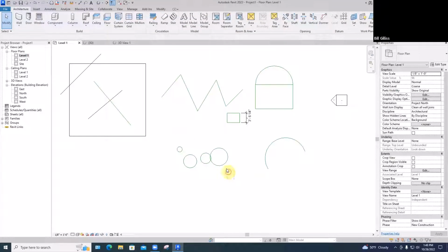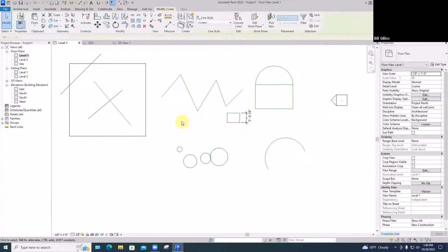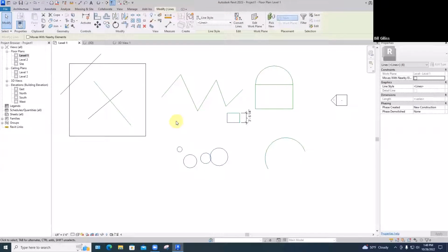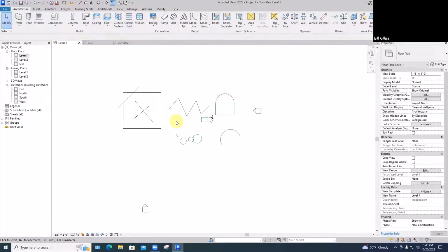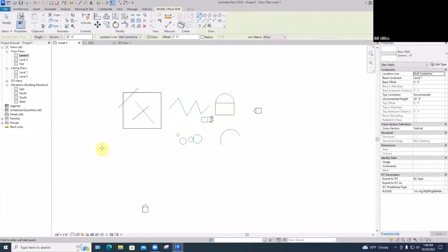Dragging from right to left, as in AutoCAD, puts up the rectangle with the dotted lines, which is a cue that as soon as anything is even touched by the rectangle, the whole thing gets picked. Then you do it, change the color or erase them or whatever it happens to be. This tabbing and selecting works for lines as well as for, let's say, walls or other things that are linear and connected.